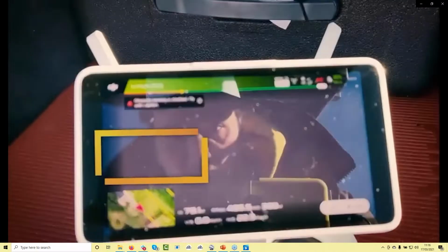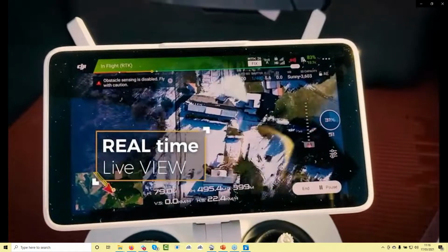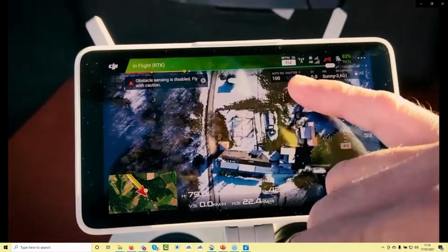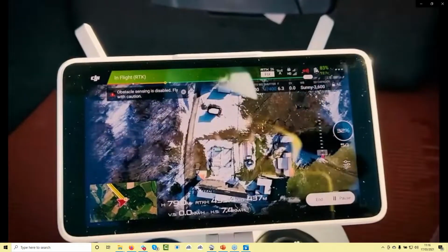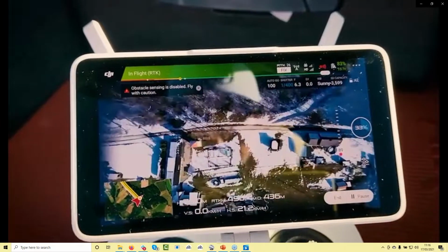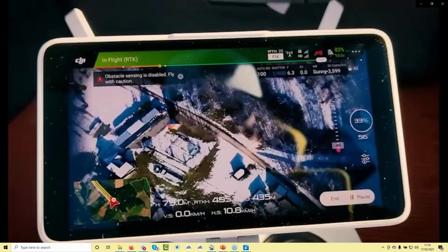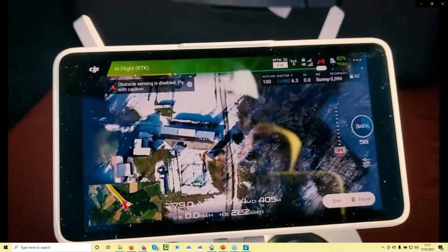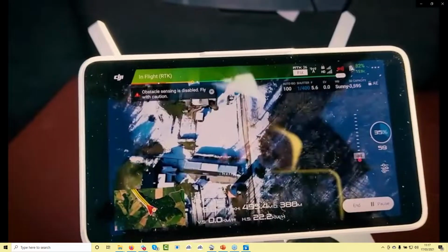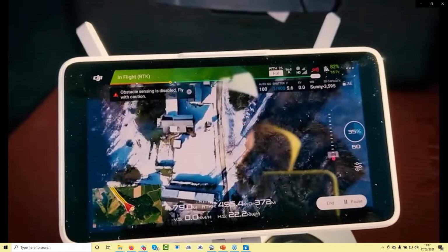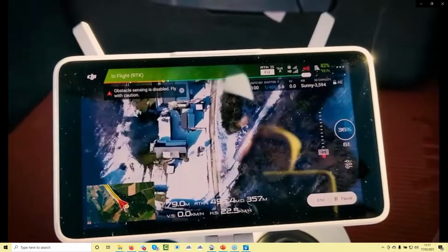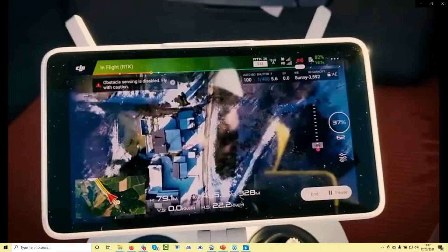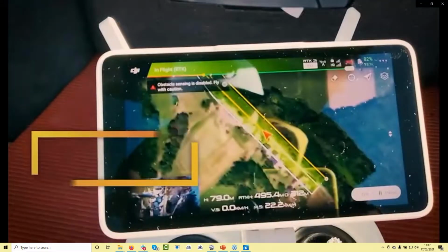If you click on image, you can see the real-time image from the drone. And why it's important here, we can see we selected the camera settings correctly, 1/400th of a second. The f value is 6.3, so the minimum would be 2.2. Maybe for the next flight, I will go to 1/600th of a second or something like that, so I can go even with a shorter time. And yes, the drone is mapping nicely. It's flying now the